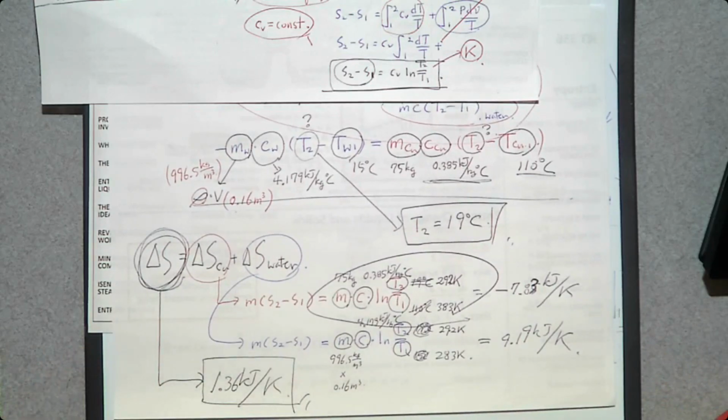So having a positive entropy change, what does it mean? It means it is not a reversible process. It's an irreversible process because there's an increase. It means that useless energy is created. So you cannot go back. If you have a reversible process, this one should be 0. If this one is a negative value, what does it mean? It's an impossible process.